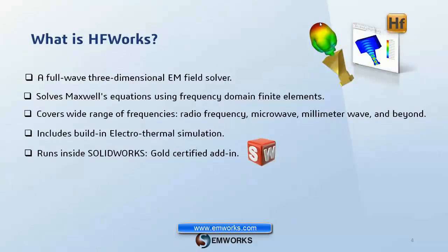HFWorks is a full wave 3D software. It's fully embedded inside SOLIDWORKS. It means it's an add-in inside SOLIDWORKS. It uses SOLIDWORKS as a CAD to read the geometry. It's based on a frequency domain finite element method. So it covers the whole band of the high frequency, going from a few megahertz to some terahertz. It can also be coupled with thermal analysis coming from the Joule effect.